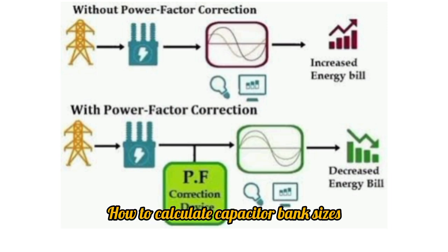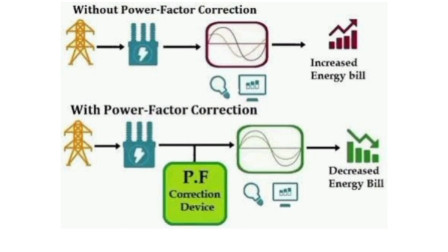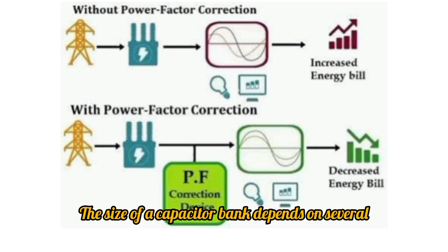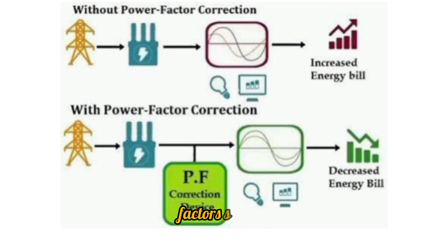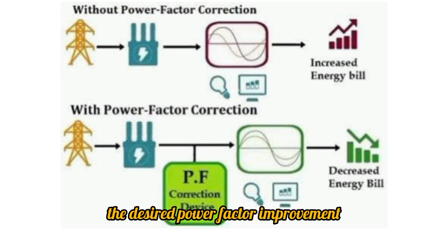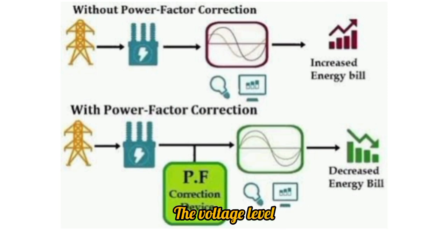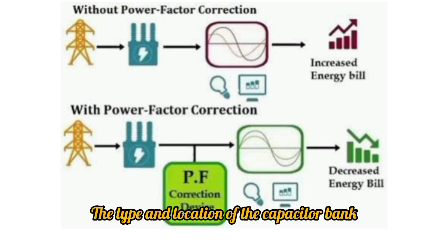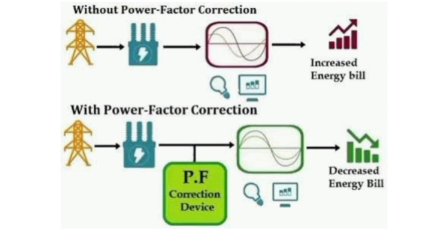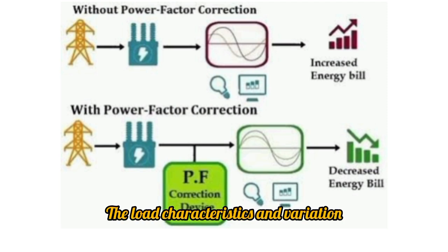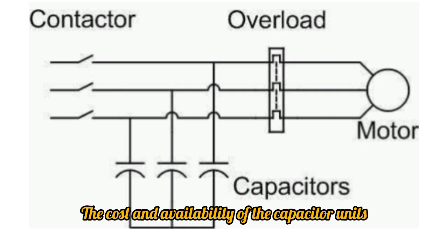How to calculate capacitor bank sizes? The size of a capacitor bank depends on several factors, such as the desired power factor improvement or reactive power compensation, the voltage level and frequency of the system, the type and location of the capacitor bank, shunt or series, the load characteristics and variation, the cost and availability of the capacitor units.